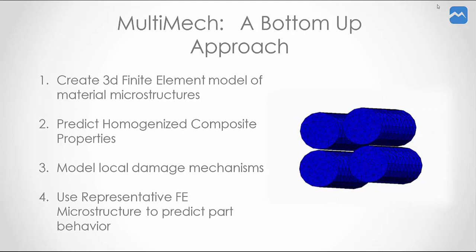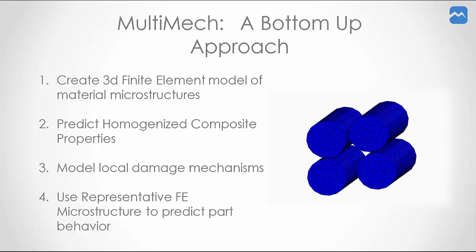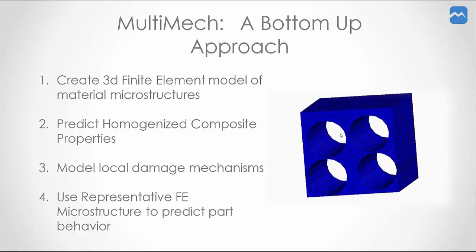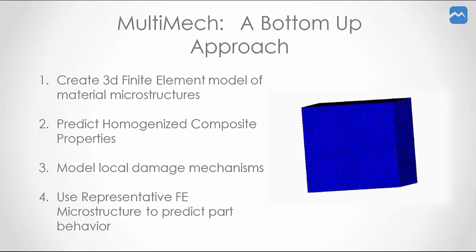Great, thank you. So, Multi MEC in one sentence is a software offering a highly flexible bottom-up approach to composite engineering. The workflow involves generating finite element models of your material microstructures, virtually testing those models the same way you would virtually test a coupon in a lab, and then directly linking those models to the solution of a composite part.